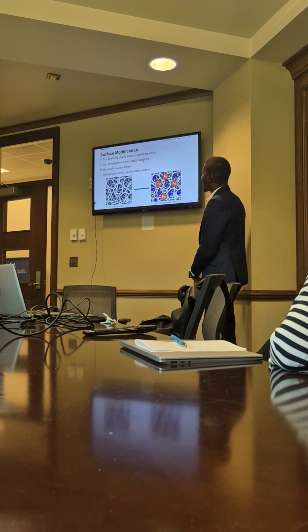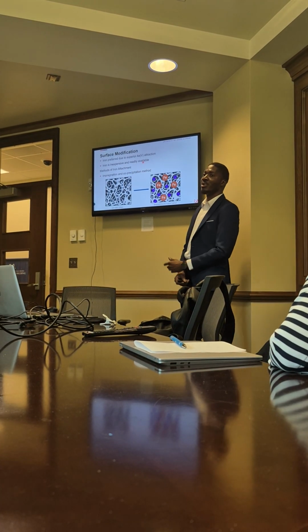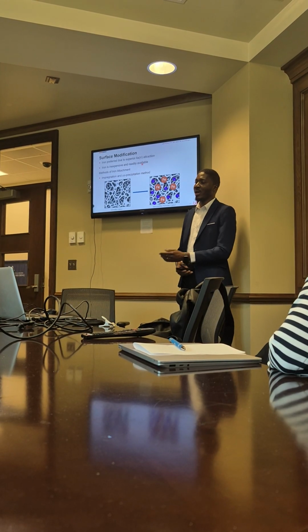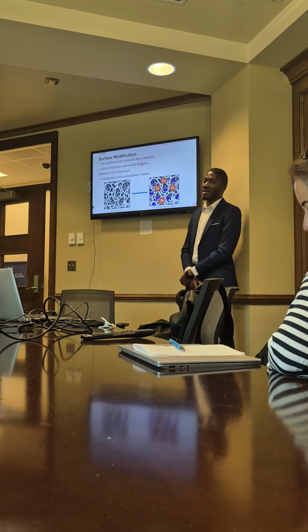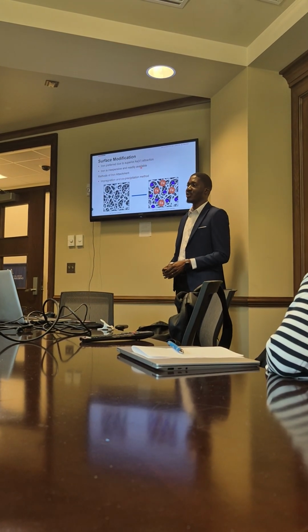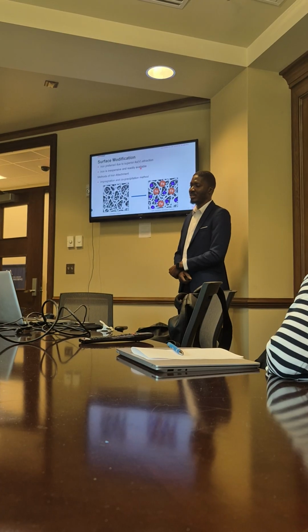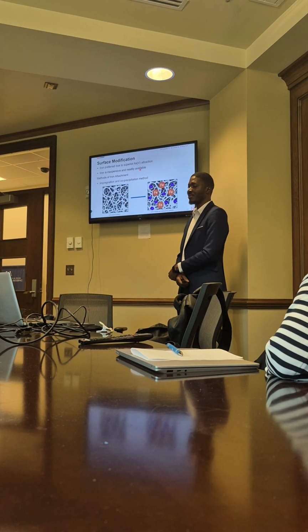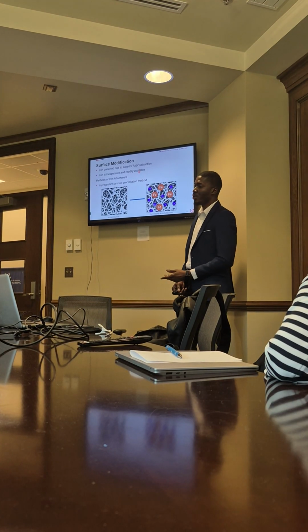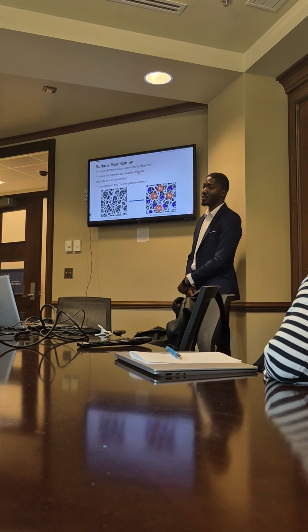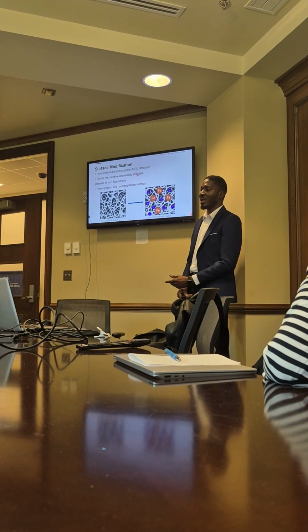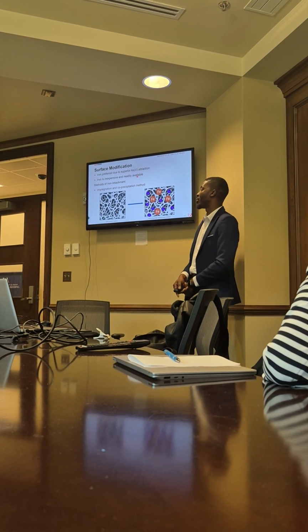And when it comes to the iron attachment method, there are two main methods we use to attach iron to a fabric or to our activated carbon. The first is the impregnation method, whereby we put our biomass in an iron solution before carbonization and we carbonize or activate afterwards. And the second method is a co-precipitation method, whereby we put our activated carbon in an iron solution and we increase the pH of the solution with a base so that iron precipitates would form onto our adsorbents.